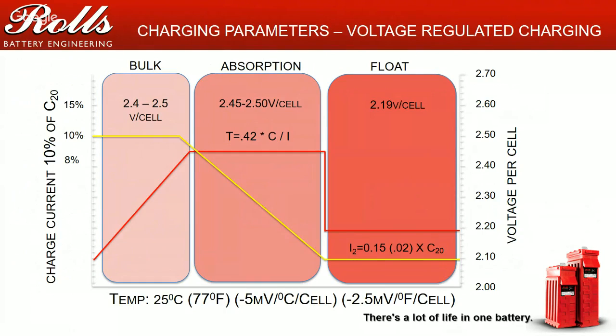As a battery manufacturer, most battery manufacturers really only care about 2 modes, your bulk and absorption time, especially for a renewable or off-grid system. Because in float, if you're an off-grid system running your generator, when you hit float your generator should be shutting off, because you're not really putting much of a charge into the batteries at that point in time.